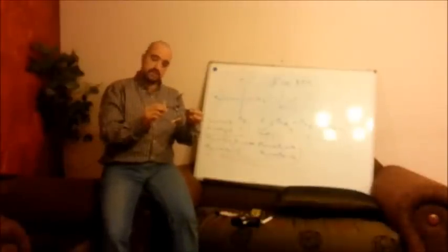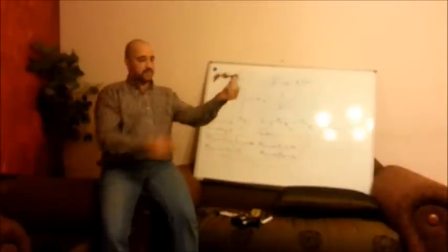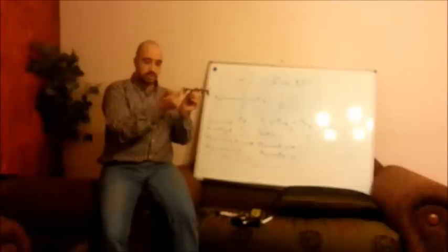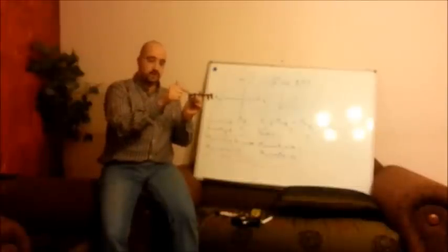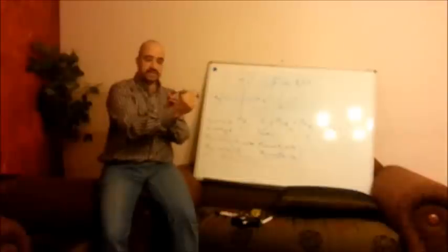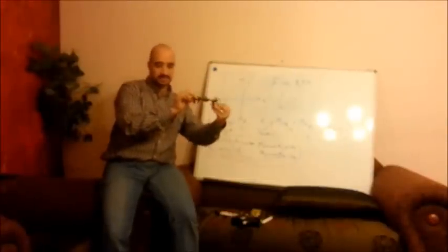As I told you, if I hold this propeller, the quad will move in the opposite direction of the propeller. Actually, when I leave it in space, the quad wants to move in the opposite direction. Because this propeller rotates in the opposite direction to that one, the two effects balance.